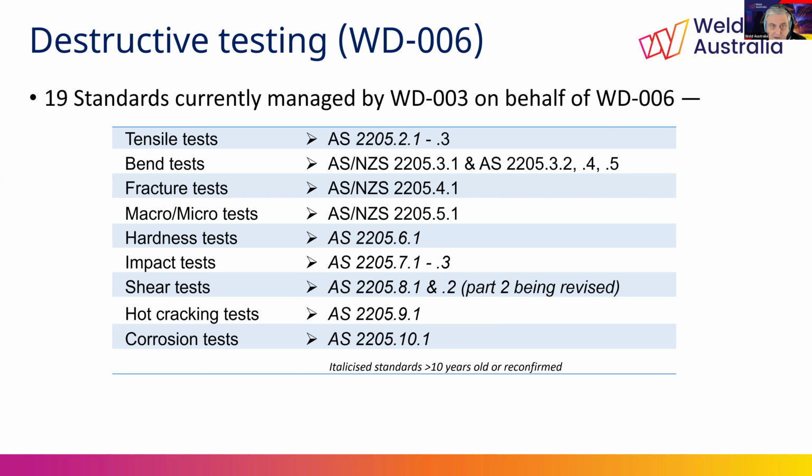Now, the weld tensile testing standard and Charpy testing standards have both been revised by ISO, but there are currently no short-term plans to adopt either of these, even though AS 1391, for example, is an ISO clone of the tensile testing standard.